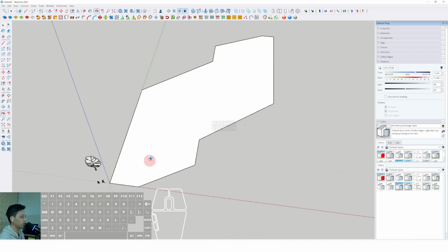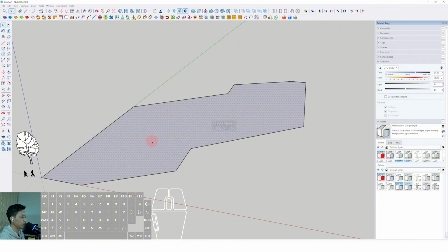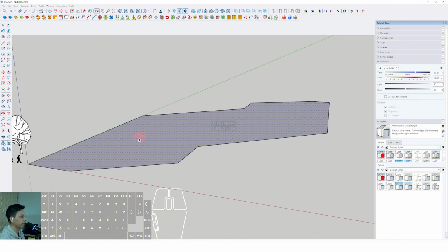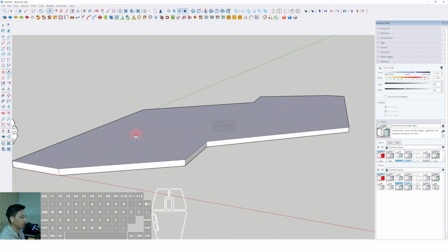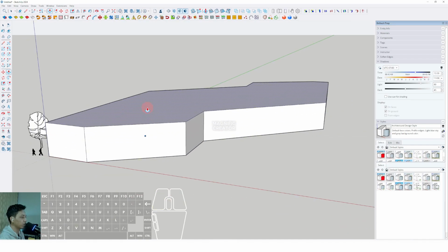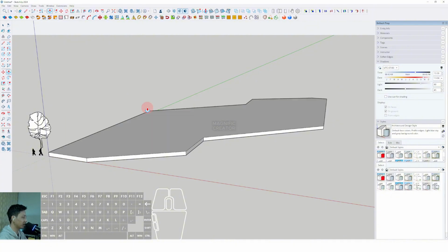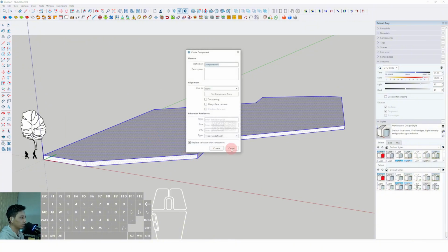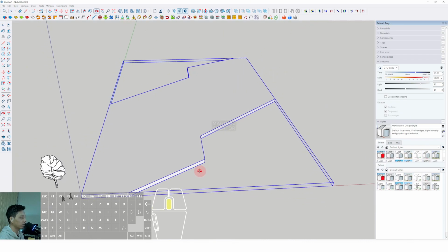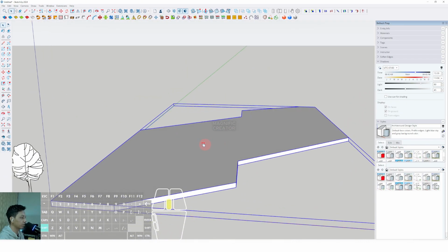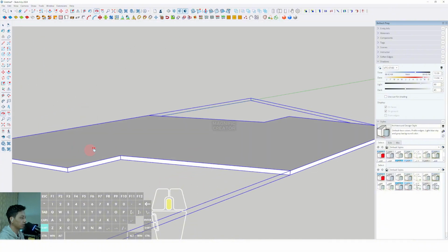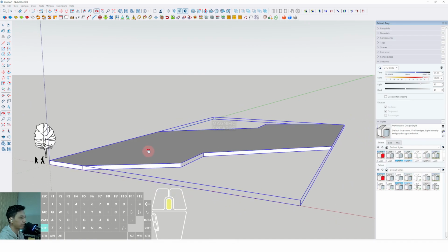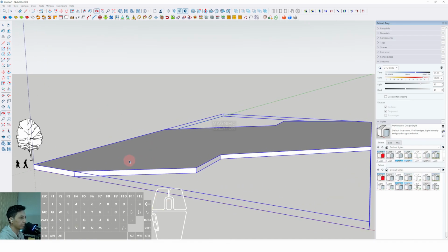Okay, now we can click the surface and select Push/Pull. Then we can click the surface again and extrude upward around 1 meter and enter. Now we can triple click, right click, make component, create, and we already have the component of this simple plane or simple slab in here. Then we can continue to duplicate it above, around 45 counts of this slab.